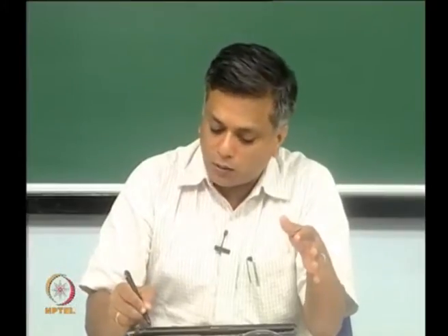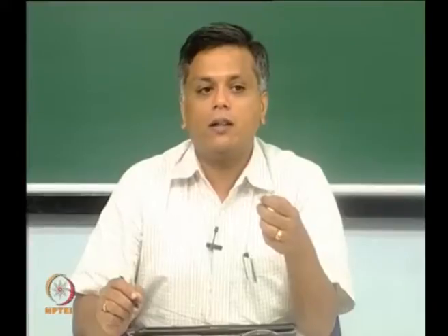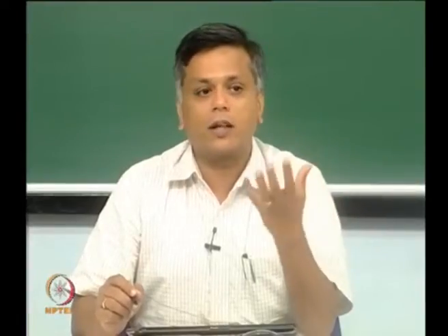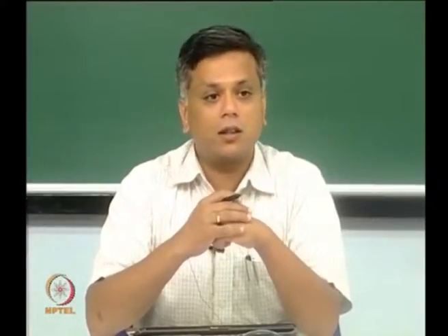What are all the forces that could act on this particle? 1, the drag force from the surrounding air. 2, if there are other particles colliding with this particle and pushing it or creating an impulse force, creating an additional force to accelerate or decelerate this one particle under consideration. Or I could have other external forces, gravity, some sort of an electromagnetic force if I am looking at other effects, etc.